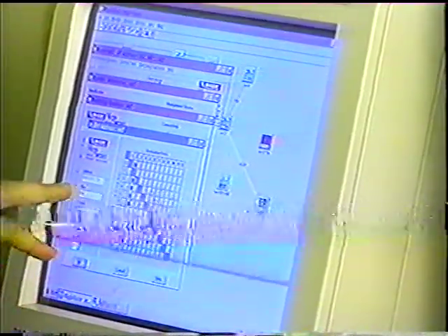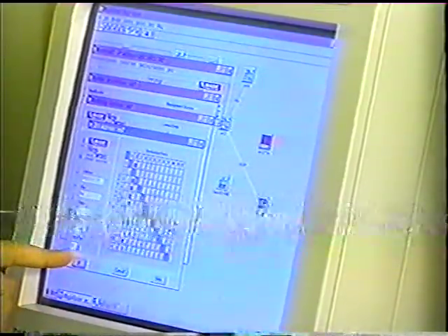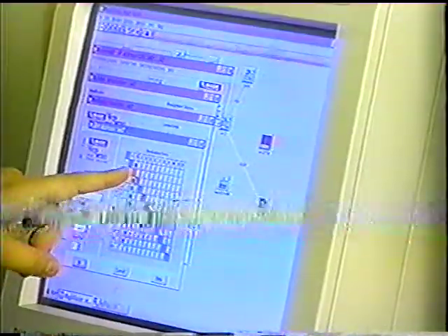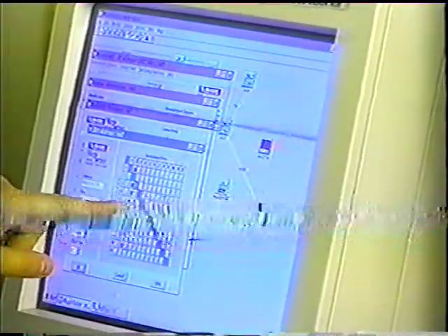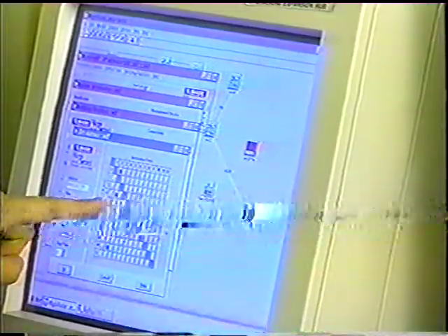What I see from this picture is that this station is located on port 2, and this station is allowed to communicate with port 1, port 3, port 4, port 5, and port 6. But I want to change it. I want to put a custom filter on this. Look what I'm doing now. This station is not allowed to communicate with segment 3, and you see what I did? This station is isolated from this.